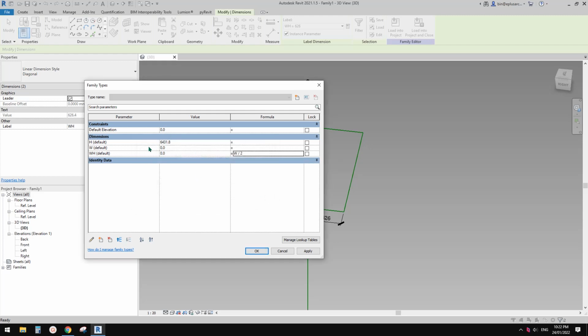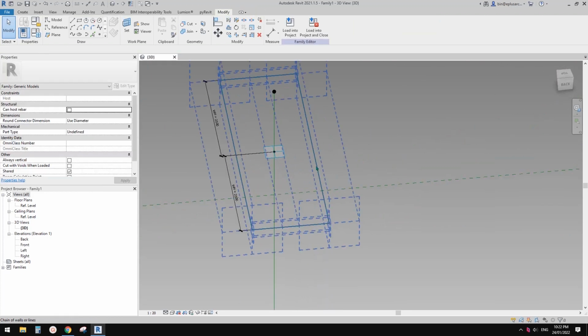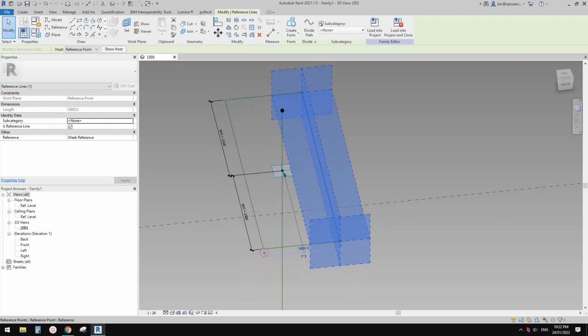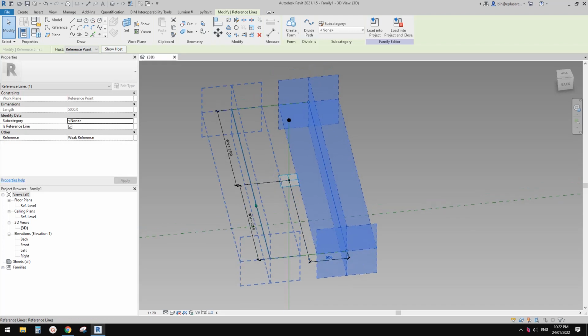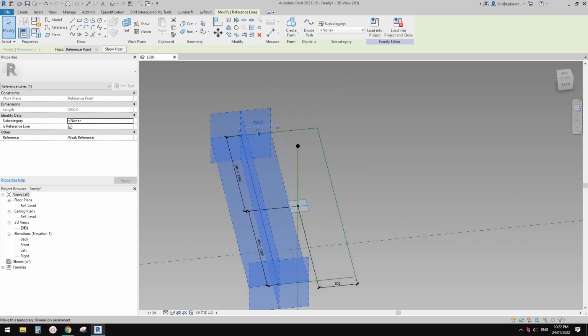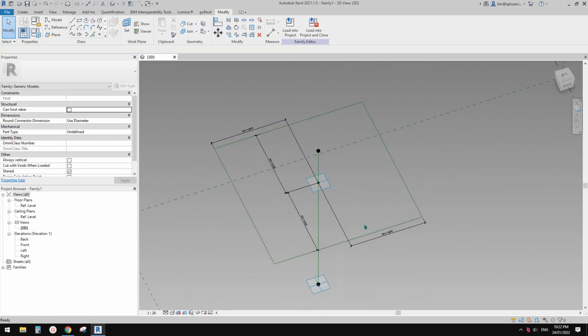Before that, let's cancel this because currently it's 0. I'll type maybe 20 meters. Apply. Oh, that's too big. 5 meters. Apply. Okay, now we just need to select this one: Tab, select individual reference line, drag this to this point, create this dimension. Tab, select this one, drag this to this point, create this dimension. Select this one, Control select, and link this to the half width. So now we have a square box profile.